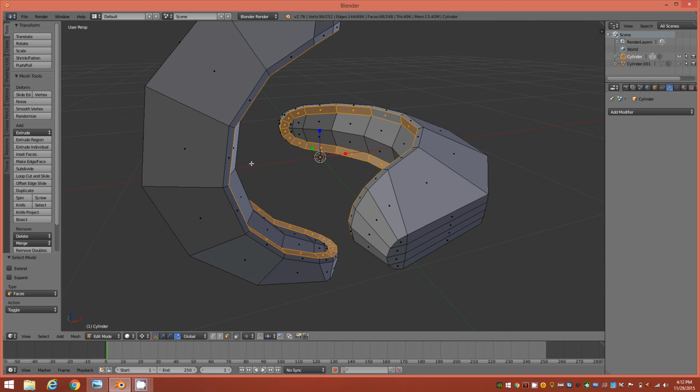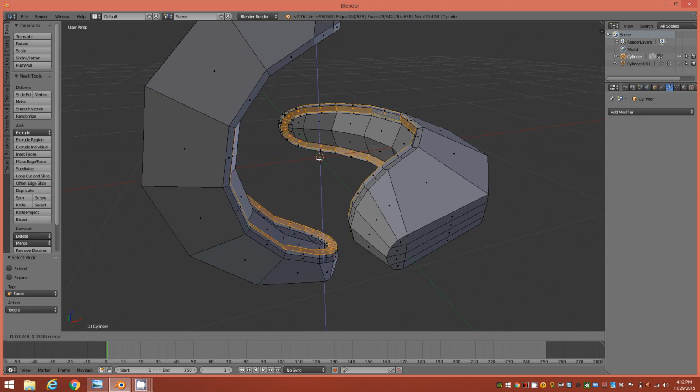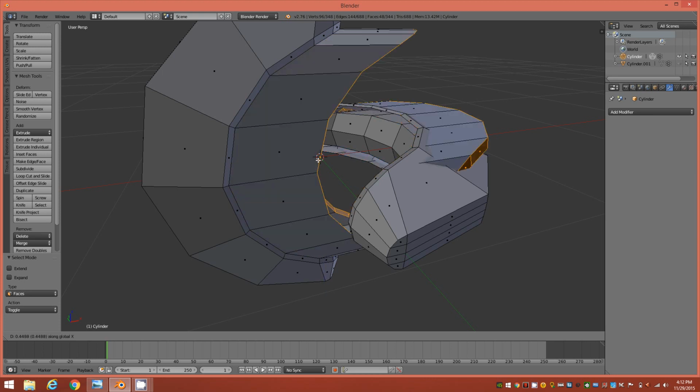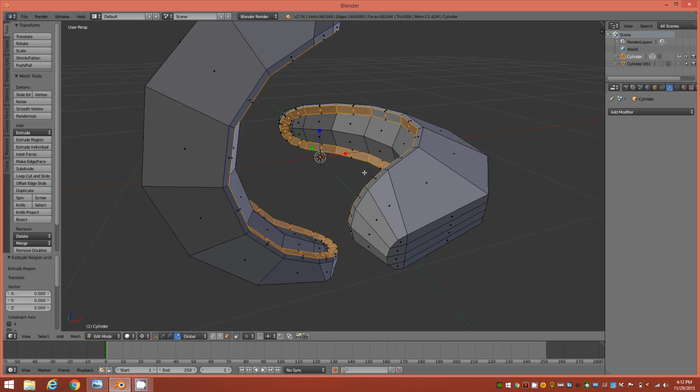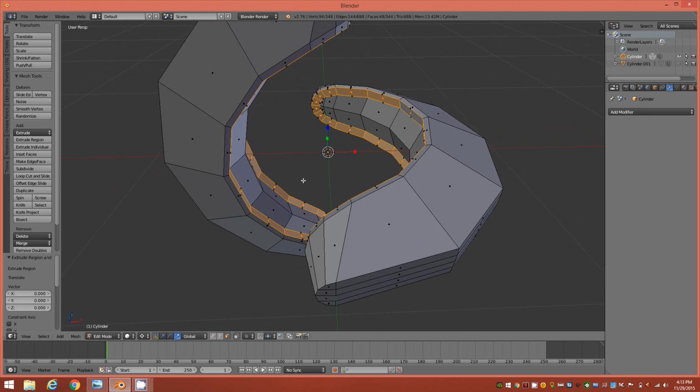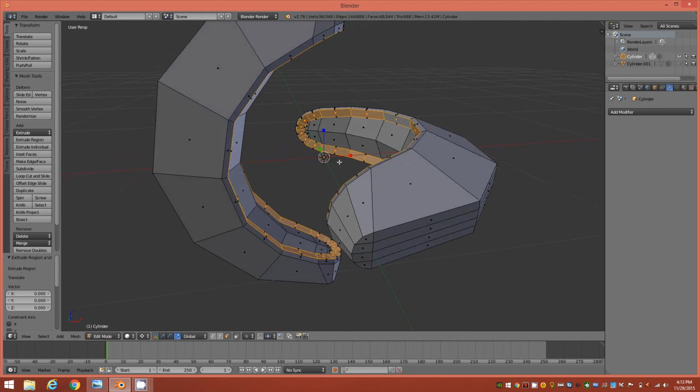Now we're going to go ahead and pull some faces out of there. So let's tap E, and holding down Control. Let me see here. Actually, E and then the X hotkey. No, that's not what we want. So I'm going to right-click and just scale it. So I tapped E and then I right-clicked, and I'm going to employ scaling to pull those faces out that I just extruded. And I think it's going to give us more control.